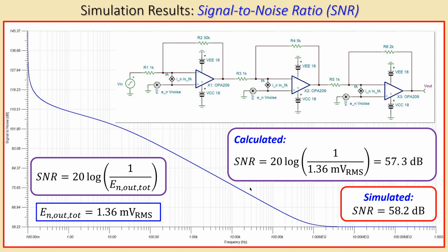Okay, that is now our example using a third-order or three-stage amplifier circuit, where we have considered the noise performance. We have seen the input and output noise performance of the circuit, and also the signal to noise ratio. We have also looked at the Bode plot, specifically the gain, and determined the effect of cascading three stages on the actual cutoff frequency, and then used a better estimation to calculate the output-referred RMS noise voltage for the circuit. That will be our ninth example.